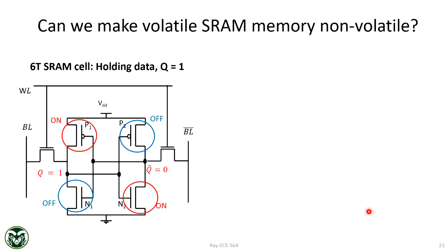for example, you think, right? You will be using SRAM in satellites, in CubeSats. So there, one issue is this radiation effect, soft error, that anytime a high energy particle goes through it, it can flip the bit. Because anytime a high energy particle goes through it, it will deposit charge. And this charge will flip this Q equal to 1 to 0. And you can see that this cell has been flipped.